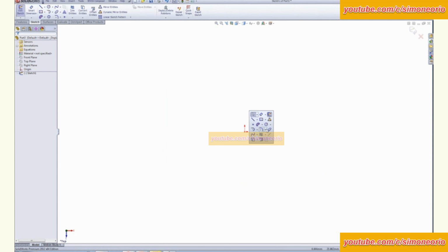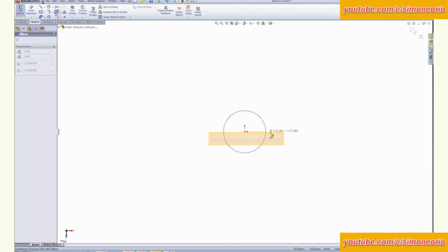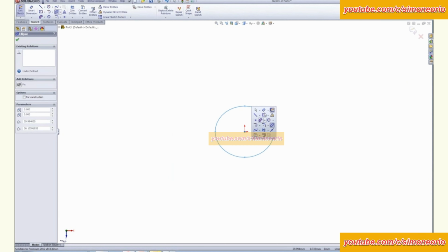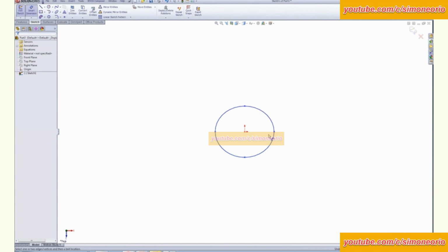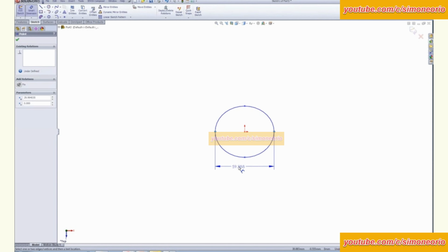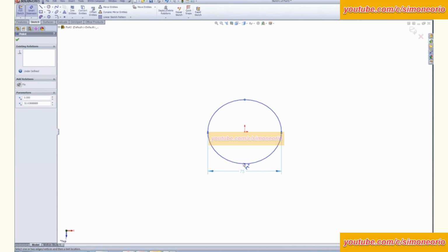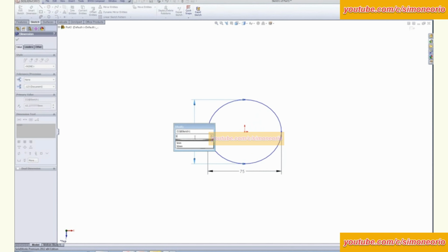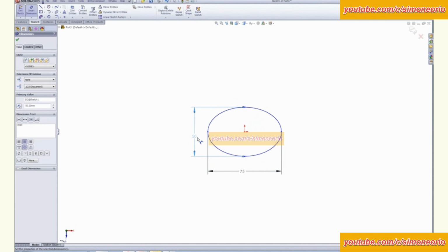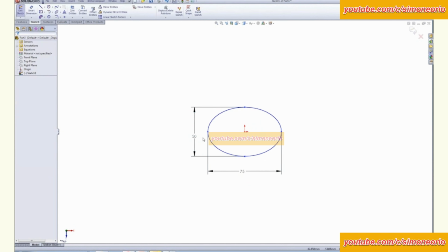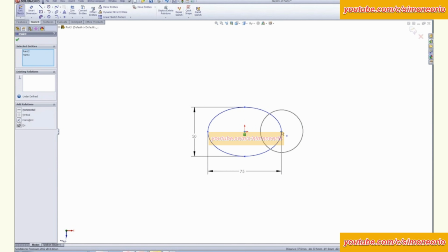Okay, but I'm going to bump my S key and grab my ellipse tool, okay, which is quite handy on there. I'm just going to come out here and just draw myself an ellipse and dimension this thing into place so that we have some parameters to go on here. We'll go 50 that way. And of course, with an ellipse, you can't just do the center, the major and minor sizes here. You have to also lock this guy in, horizontal or vertical, in that regard to make it fully defined.